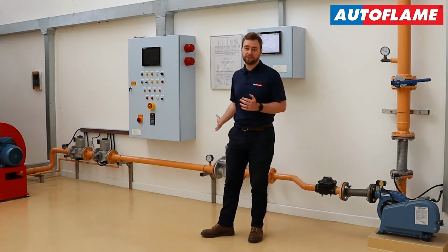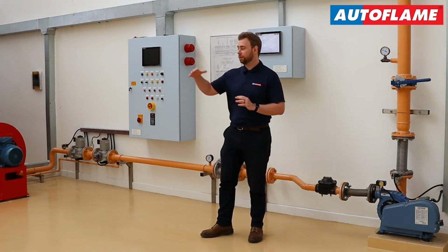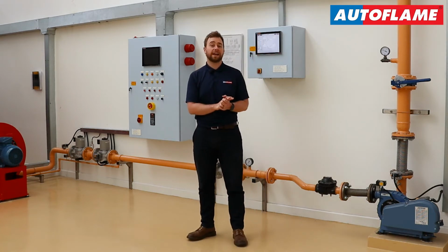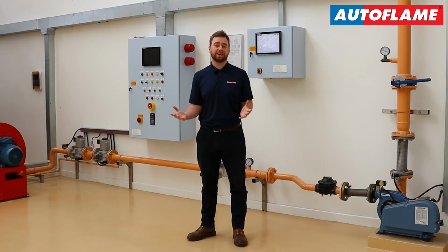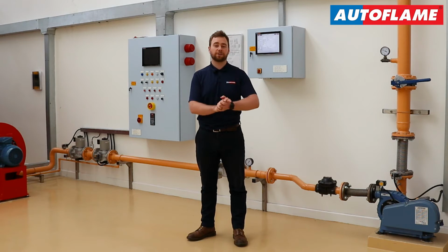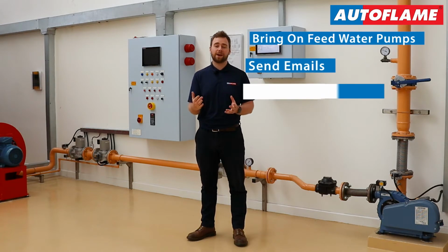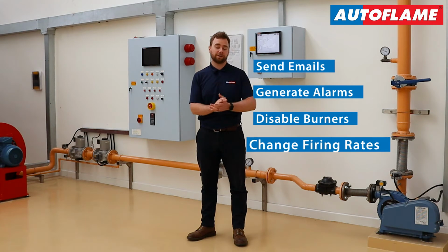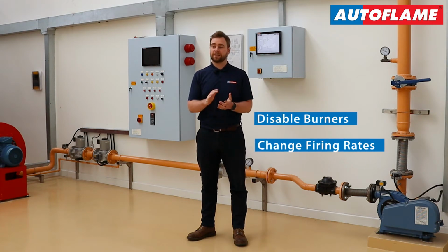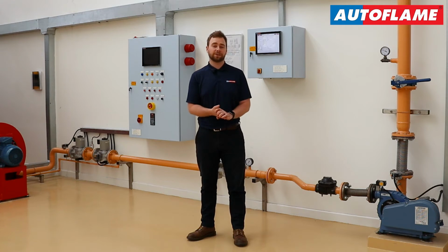Maybe there's multiple points on your gas train that you also want to monitor. You could monitor the level of an oil tank, we could take an input from a level sensing device in your DA tank, and we can generate various points of control, such as bringing on feed water pumps for your DA tank. We can send emails, generate alarms, even disable burners or change firing rates if we want to. So let's have a look on the DTI at some more of those intricate details of those rules.